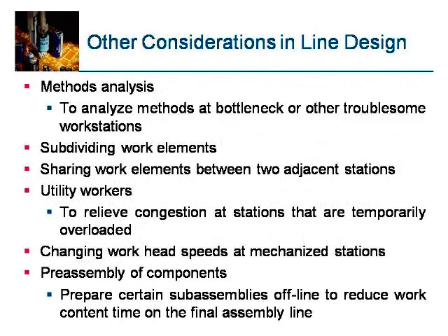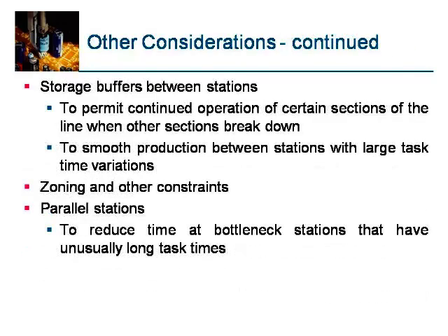Other considerations in line design. Methods analysis: to analyze the methods at bottleneck and other troublesome workstations, subdividing work elements, sharing of work elements between two adjacent stations, utility workers, changing work head speeds at mechanized stations, pre-assembly of components, and so on. Storage buffers between workstations permit continuous operation of certain sections of the line when other sections break down, and smooth production between stations with large task time variations.